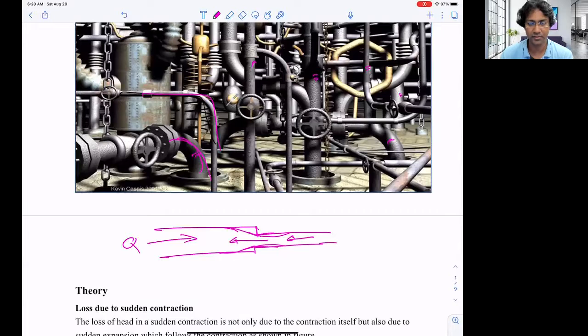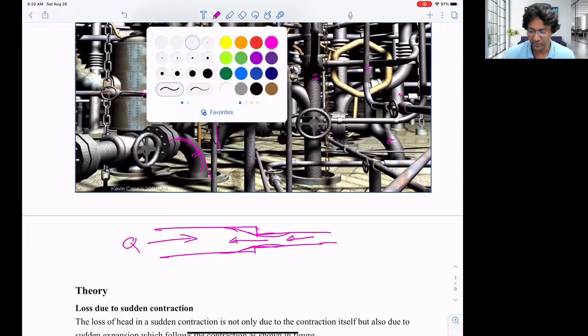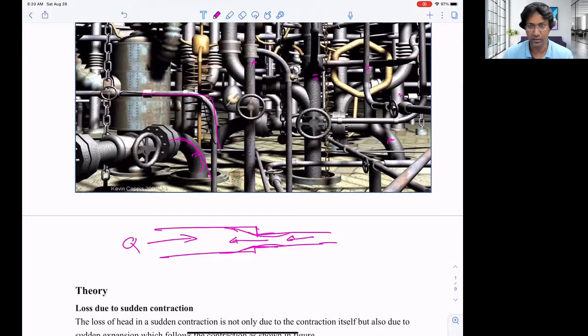Frictional loss is mainly because of the roughness of the pipe, right? That is called major loss. We know that by this time. But for settings and fittings and bendings and different types of contraction and expansion, we'll have losses that are not even up to that magnitude that we saw for friction. So that's why these are called minor losses.